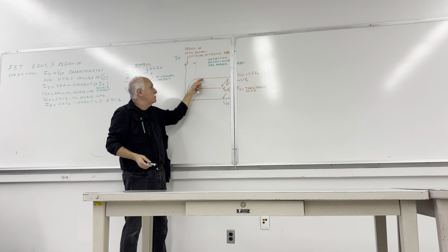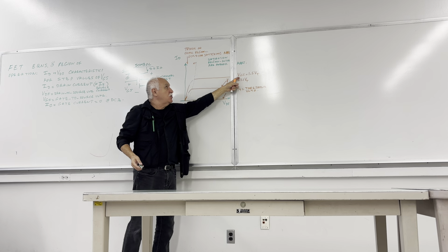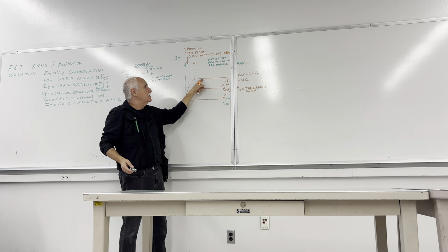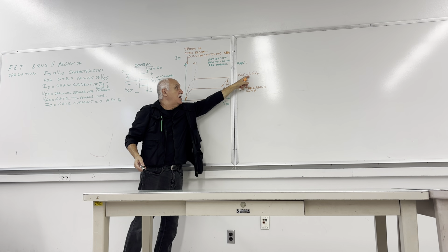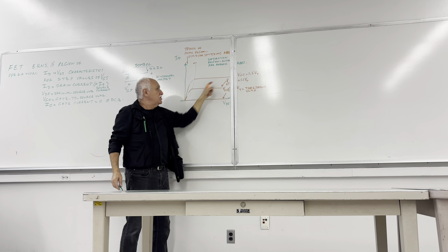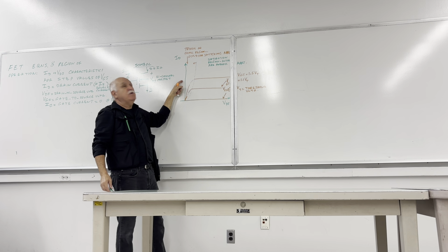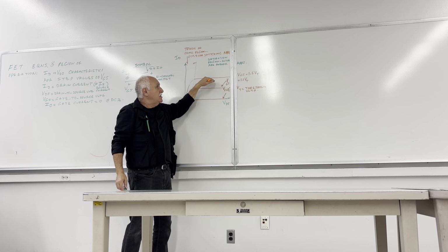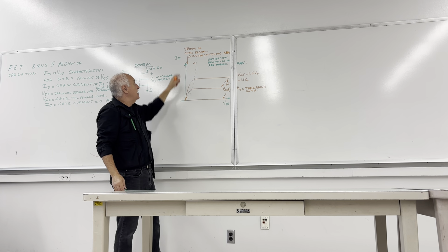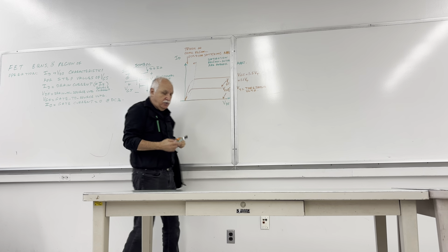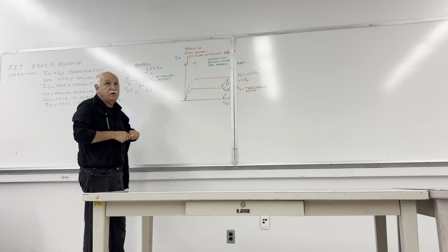Obviously, see? It's determined solely by VGS, not by the VDS. You can be here, you can be there, as long as you are at 50% more than VT. Doesn't matter what is VDS, your ID will be fixed, a fixed quantity. So when that happens, then your ID becomes dependent on the VGS very strongly. So we can create another curve, very practical.